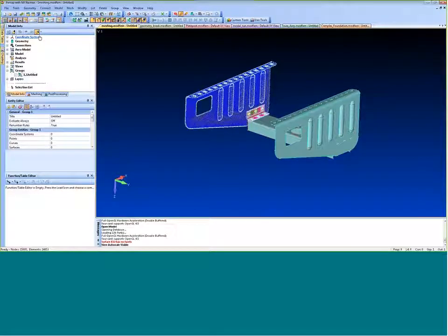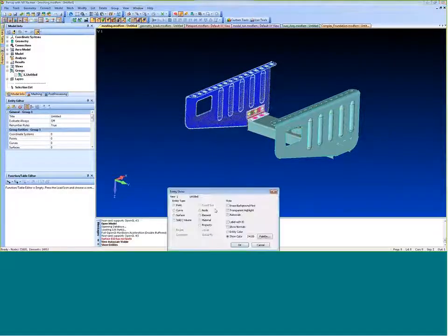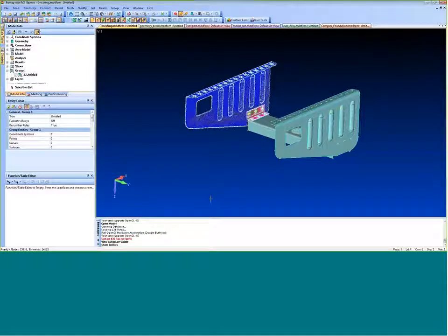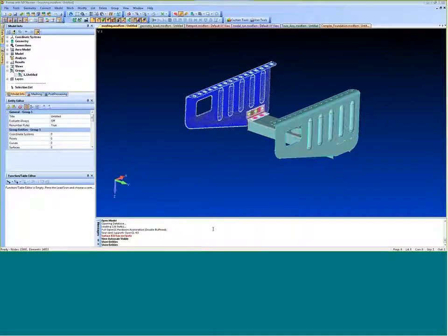But what auto scale does, and it's a nice feature, is zoom in automatically whenever you select your group. You can activate that by going into this drop-down menu and selecting auto scale to show entities. If you don't like using it that way, you can go to Windows and Show Entities, and here it is. Or if you like to be fancy and use shortcuts, Shift F12 takes you back to it right here.